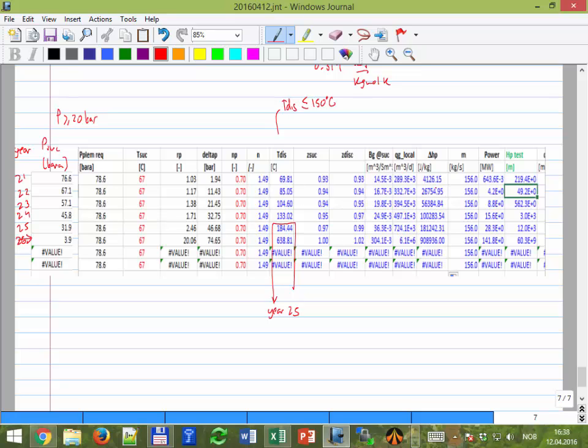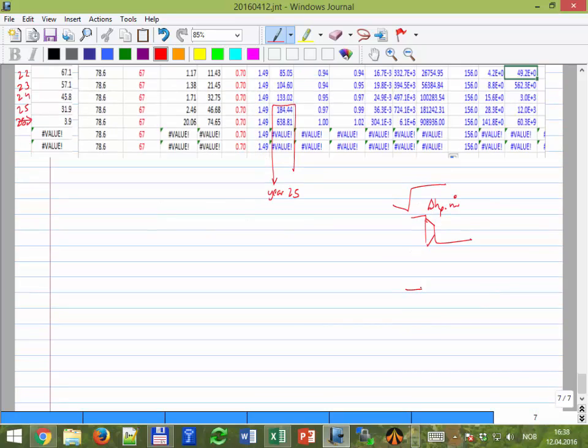We have Q local, and here we have no constraints in power. What are the constraints in power? 22 megawatts, because we have two compressors. Is it the same? Because what we are doing here is assuming that we have one big compressor and calculating delta H times flow. Is it the same as doing this?